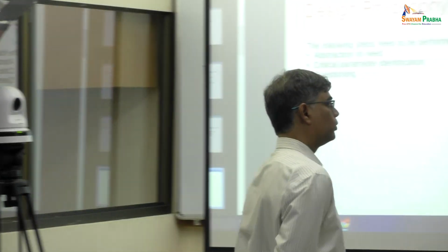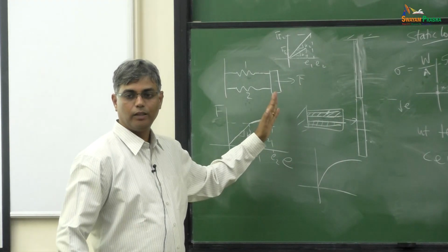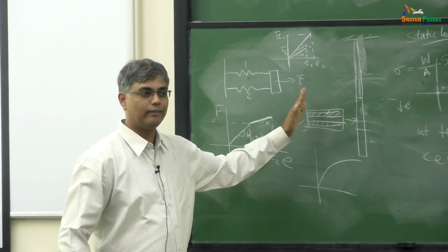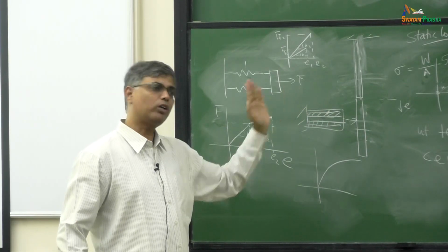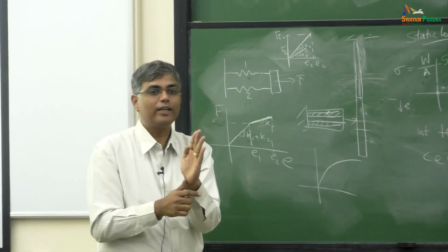By the way, there are two kinds of loading methods that materials undergo. One is called displacement control. How much it is going to extend, that much force, whatever force. If the force has to reduce, it will reduce, but you want to control the displacement.